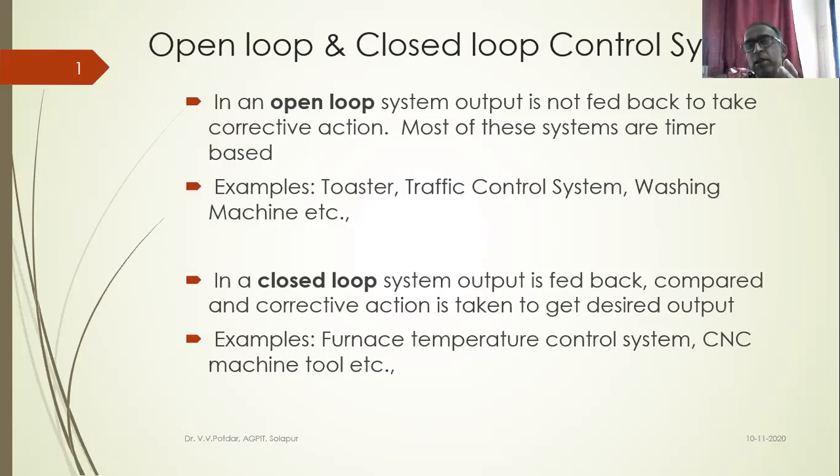The yellowish tinge will give me different light reflection. The light intensities will be different. The whiter one will give me different light intensity. So accordingly, I can calibrate those sensors. Whatever is the voltage generated by those photosensitive sensors, that can be correlated with the quality of the toast. So that's how we can convert this open loop toaster into a closed loop toaster.